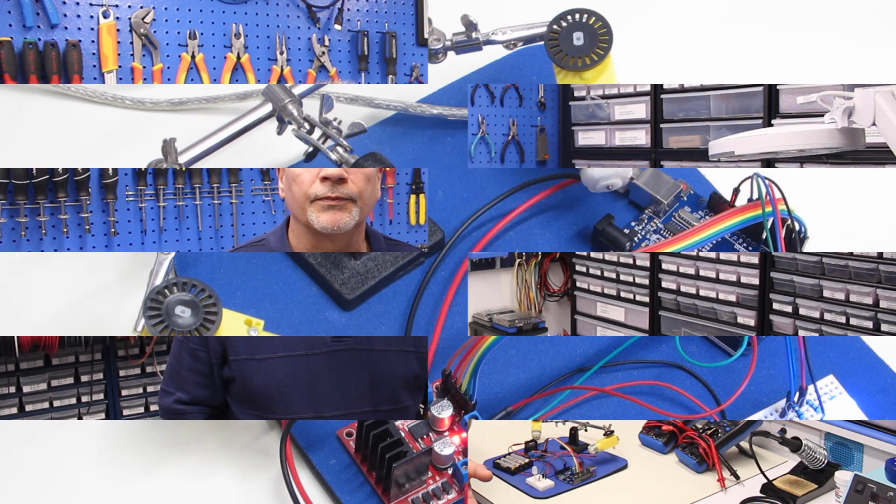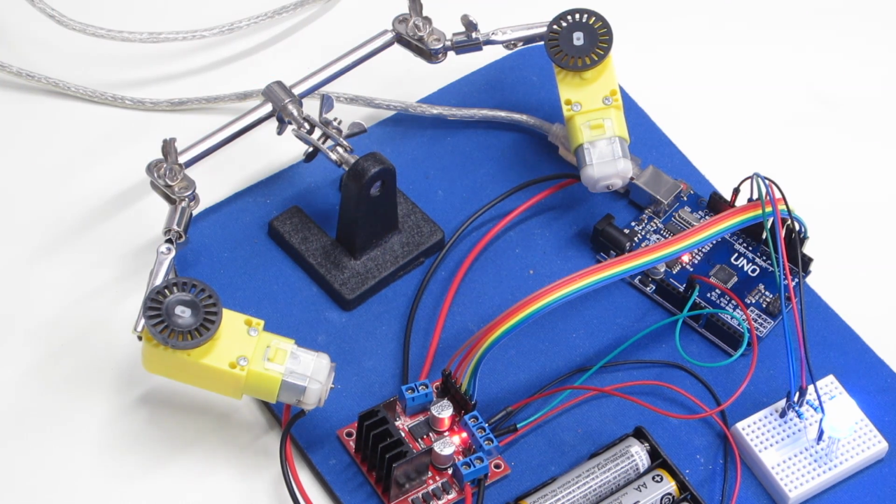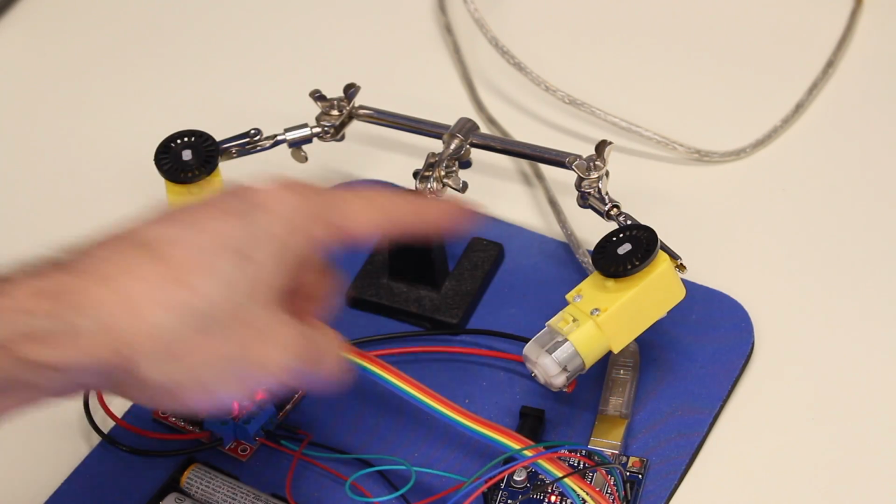And I'm going to show you how to do that, because just like the Arduino IDE, you can add new libraries into your XOD IDE when you're dealing with a component that wasn't part of the original IDE. So let's take a look at how we add a library to XOD and how we use it to control the L298N motor controller. So now that we've seen how to use XOD to control our RGB LED, let's move on and control our two motors.